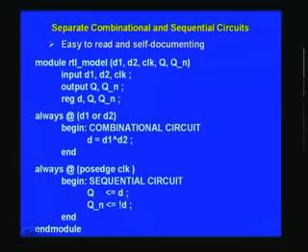And once you have just two blocks, always block. We will come to this statement a little later, and this is an always block which you are once again familiar with. This is just a combinational realization. Whenever D1 or D2 changes, for example, if D1 was 0 earlier, now it changes to 1, or let us say D2 was 1 earlier, now it changes to 0, only in the event of a change occurring, this will be processed.